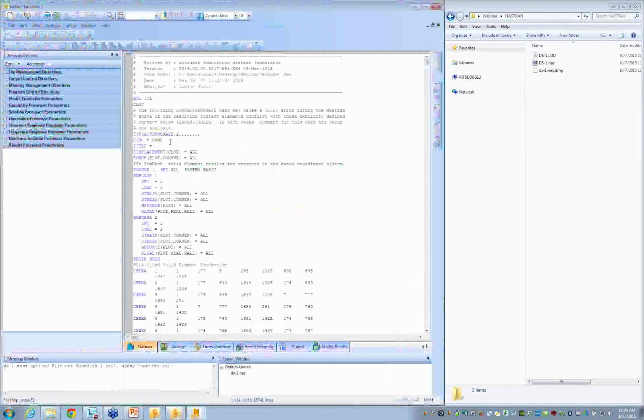In Nastran, there's a detection tool for contact between parts, and it is written to the Nastran deck from Simulation Mechanical as one of the top lines. So this line right here, the contact generates, detects contact between parts. But of course, if there are no parts to define contact, it will fail to define it, and it may end up giving you an error message.